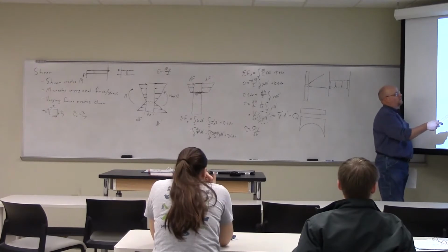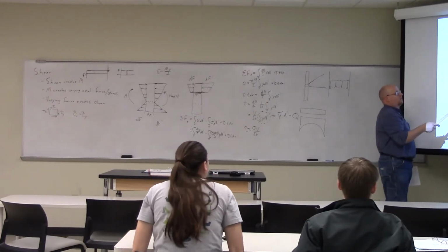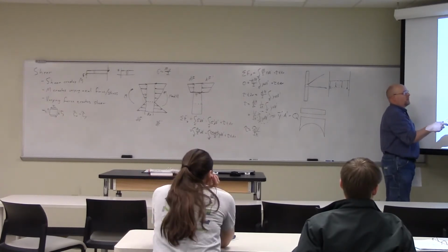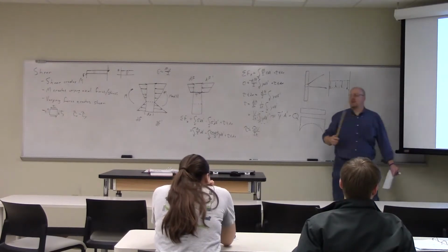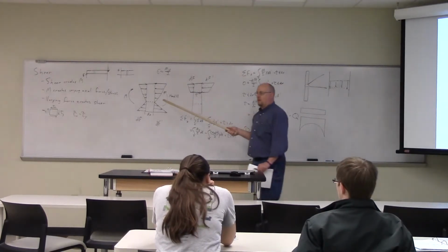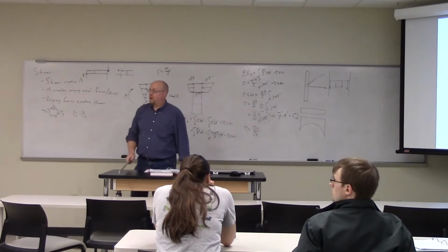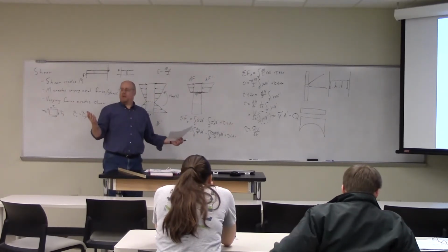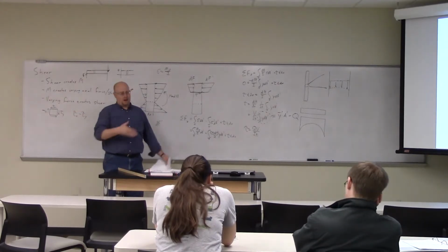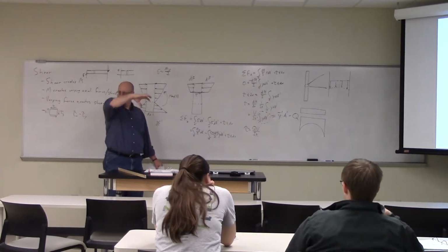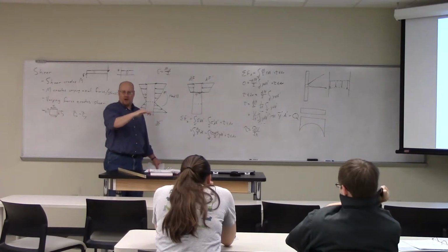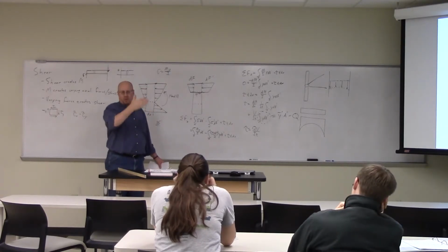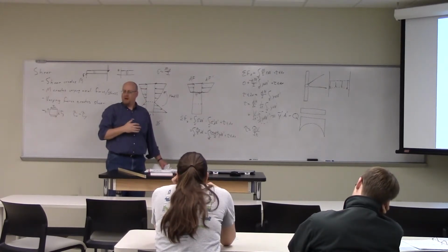So when the plane on which you're analyzing the shear stress is not perpendicular to the edge surface, this analysis falls apart. But the analysis works as long as you have perpendicular sides. Think about most beams, like an I-beam. You're going to stress it orthogonally, and so the sides will be perpendicular to the direction of the shear stress you're trying to find.